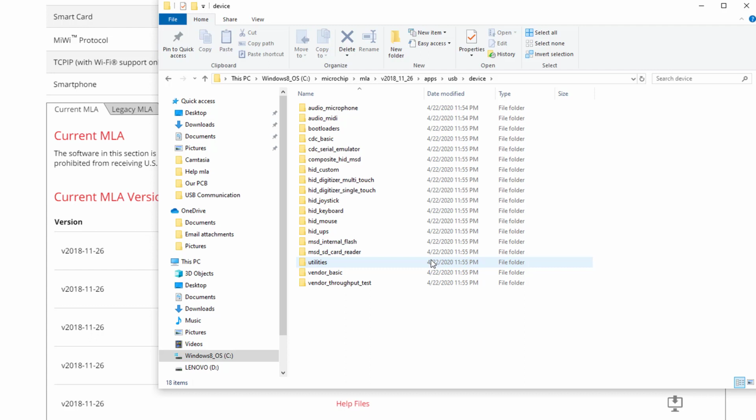You can't just copy a project folder from this directory. It won't work because it has dependencies with other files in other folders, and sorting those paths will really be a nightmare. The best option is to package your project. This will create a zip file with all the required files and folders to run your project from a different location. Always do this. Don't modify the original example project, as you might need them later. Okay, let us see how you can package an example.